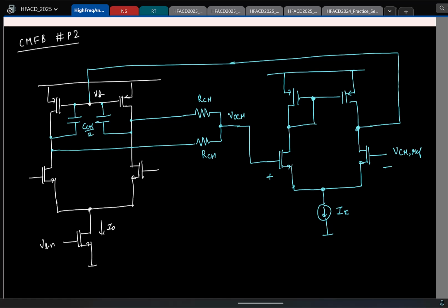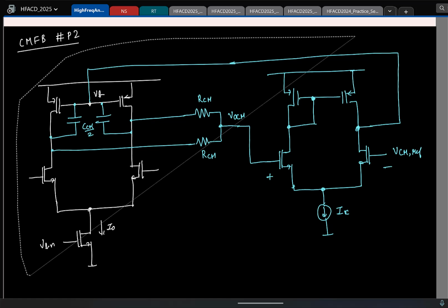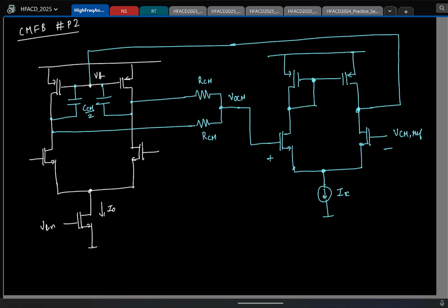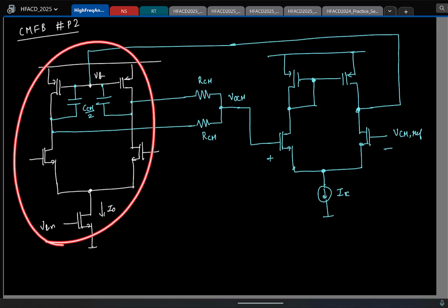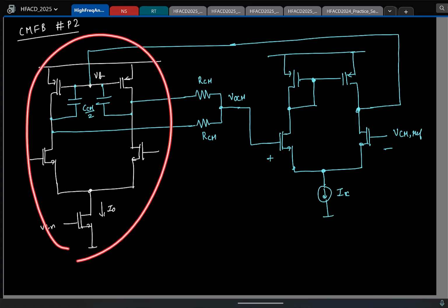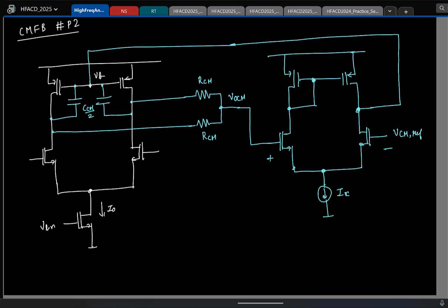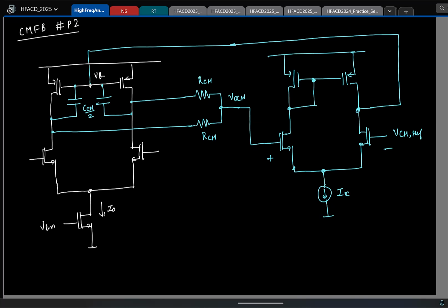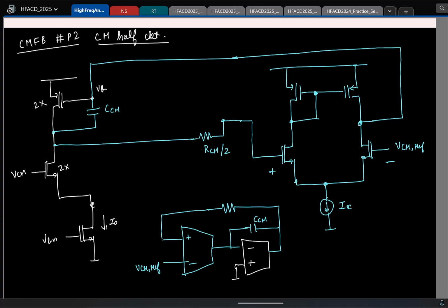So here there might be a point of confusion. I just want to clarify that the actual differential amplifier that we are making is still a single stage OTA. Now in order to set the output common mode of this single stage fully differential amplifier, we need an additional amplifier, and with respect to the common mode signals, this entire combo looks like a 2-stage OTA.